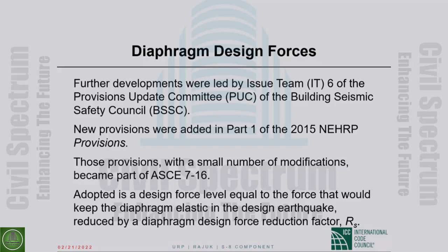That is a necessity. If from the outside you want to create the impression there is no gap, you can put something like plasterboard or something that will easily crumble in an earthquake, not interfering with the deflections of the two parts.